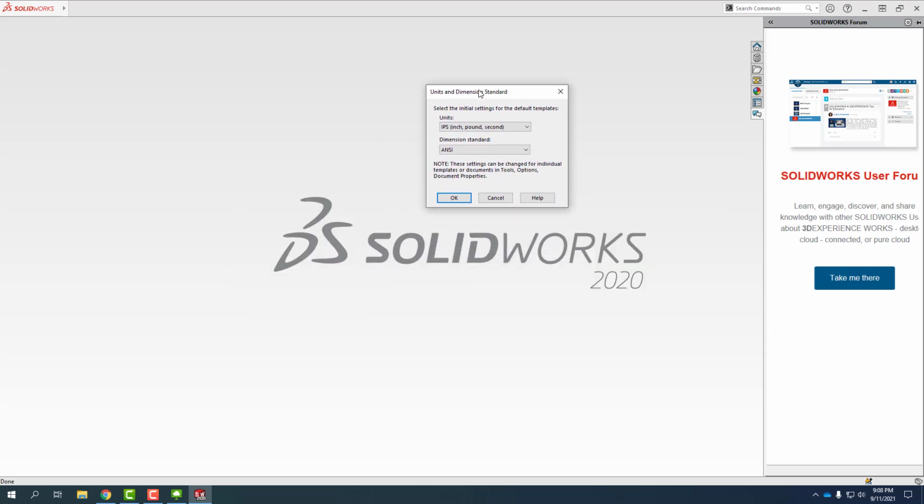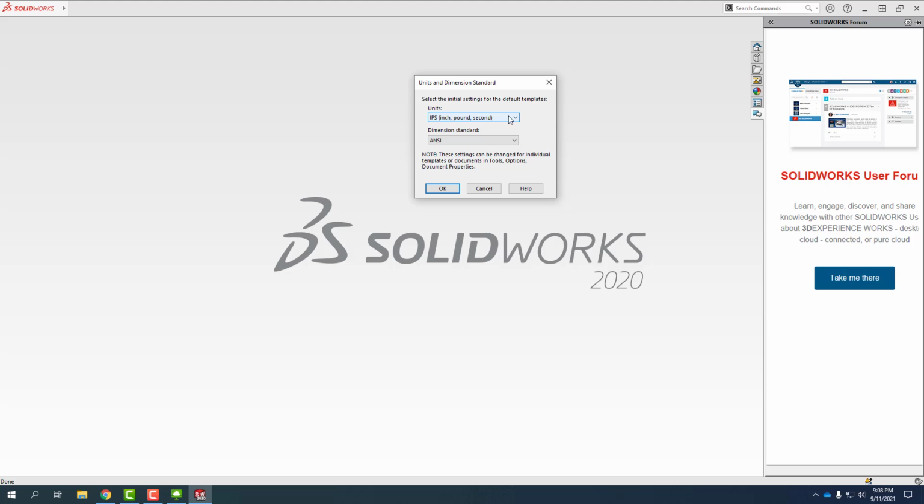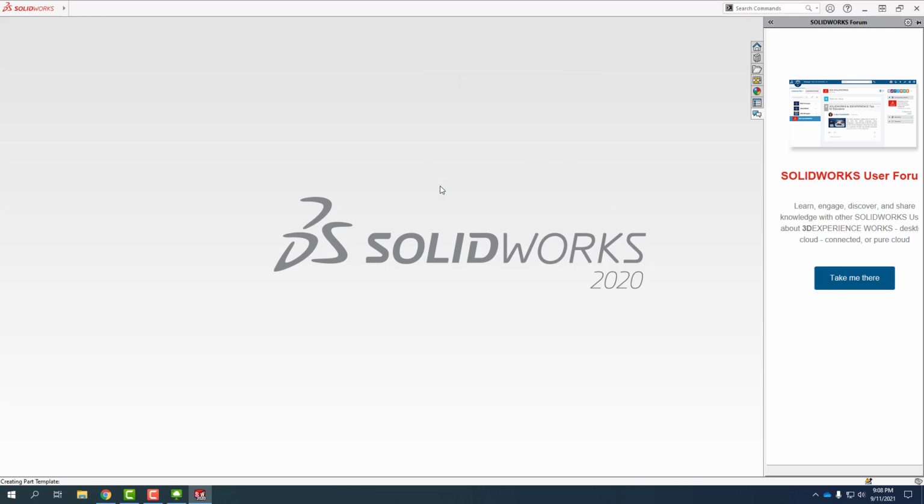And this is the one thing I'm going to want you to change. Change our units. We'll work in default millimeter gram second units. And the dimension standard we will do is ANSI. Actually, let me take that back. Leave it in inch pound second for right now. But the one thing is you want this to be ANSI. Sometimes by default the installation might be in ISO. These are dimensioning standards, but I can describe it more in class. But for right now, set it so that you're in ANSI, because this will set up your templates for your parts, assemblies, and drawings. So we'll select OK.